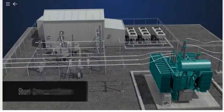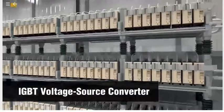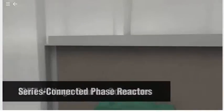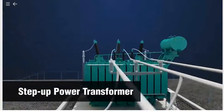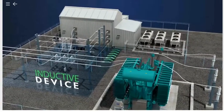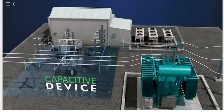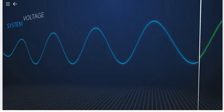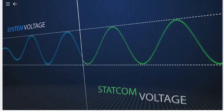A modern STATCOM is a shunt-connected device that is comprised of an IGBT-based voltage source converter, connected to the transmission grid via series-connected phase reactors, and a step-up power transformer. A STATCOM can act as an inductive device, absorbing reactive power from the grid, or a capacitive device, producing reactive power to the grid. The basic operating principle of a STATCOM is that it produces a voltage waveform in sync with the transmission system voltage.